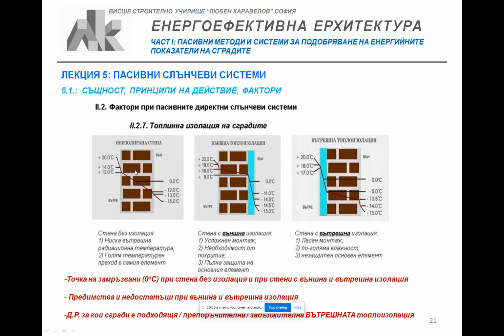happens in the main building material, somewhere in its thickness, which means that all the freezing and condensing happens in the main material of the building element, and it is very destructive. Both processes, water freezing and condensing, are destructive. When water freezes, it enlarges its volume and thus mechanically destroys the material around it. Then when it gets warm, it liquefies and washes away, but the caverns that were created stay and gather an even bigger amount of water that again freezes and destroys even more.